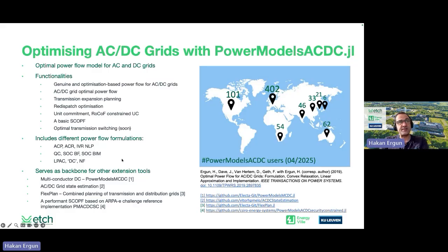It also comes with a list of different power flow formulations, because when we are looking at long-term planning problems, in order to increase the tractability of the models, very often we want to linearize our power flow equations to be able to use more performant solvers. However, of course, when we need to look at how to do voltage management, how our losses are going to be affected, and so on, then we also need the full set of nonlinear equations.